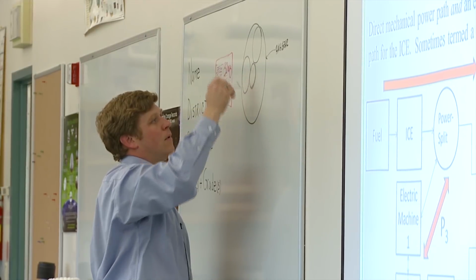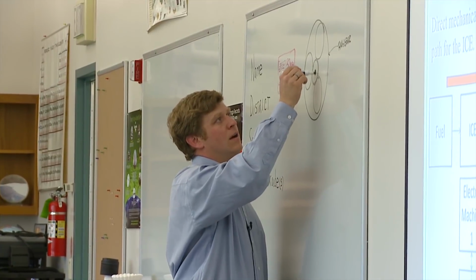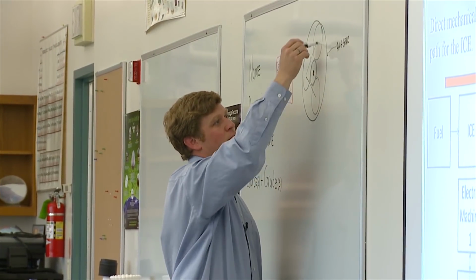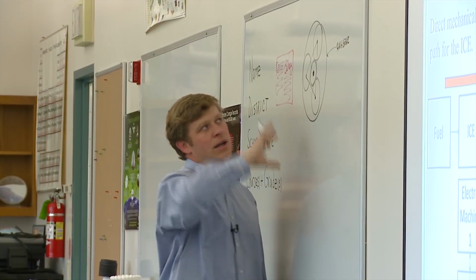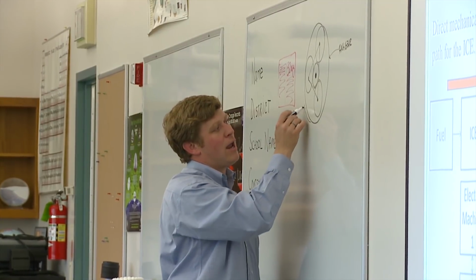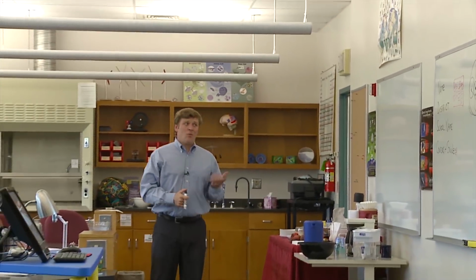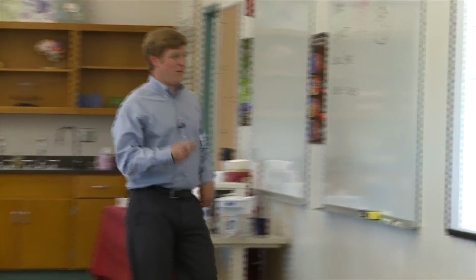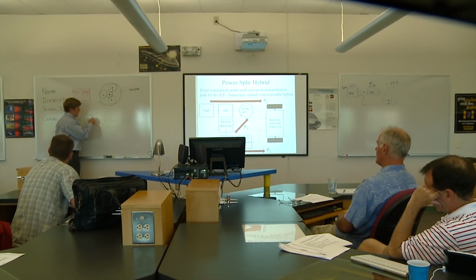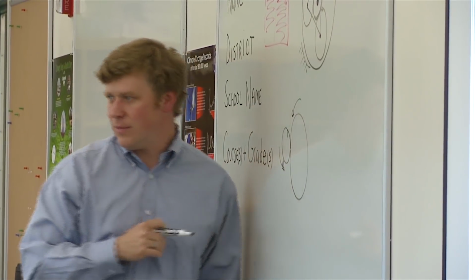And all of these things are mounted on shafts, so that this is what's called a planet carrier. So it's just a piece of steel that carries all those planets and rotates and stuff like that. All of these, in fact, are able to spin about this center axis here. Okay. So the global idea of a single gear set is that there's only one degree of freedom, right? If I turn this one, then this one must turn at some speed ratio that's proportional to the number of teeth in the gear and all this kind of stuff, right?